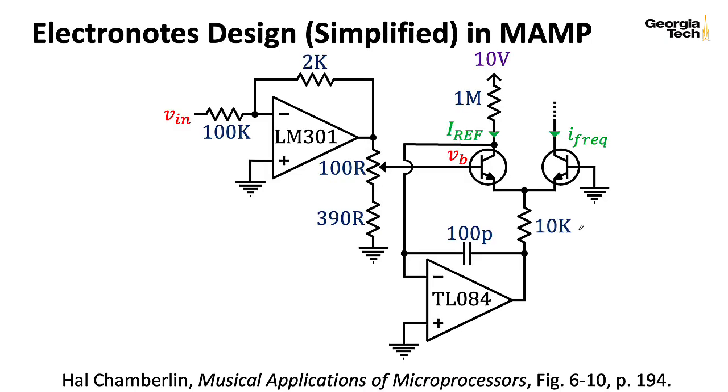Now, one thing you might have wondered back when I showed a slide like this is why did we put the voltage into here and put the ground here when that gave us a minus sign that we wound up having to use an op amp to provide an inversion operation to get rid of? Why didn't we ground what we had over here and put our input in over here? Well, inevitably, you're going to want to add up some control voltages in a nice way anyway. And the most convenient way to do that is with an op amp in this inverting configuration that gives you this nice mixing node here. So if you're going to have something that inverts anyway, you might as well put in something that will kind of invert it back.